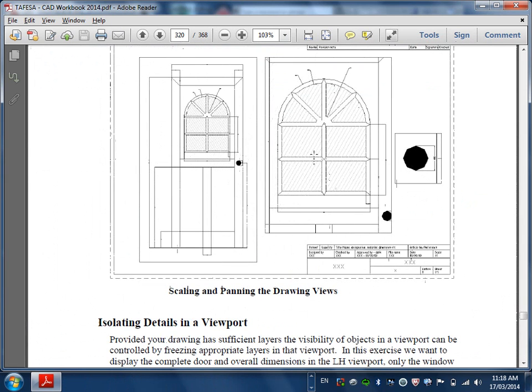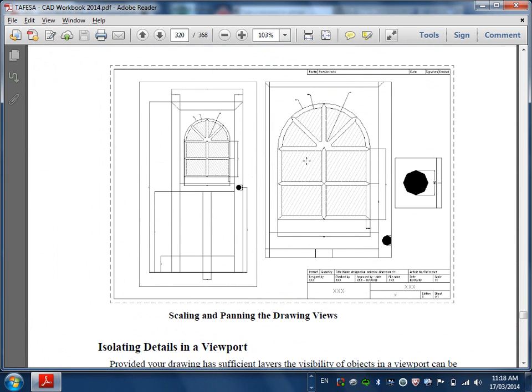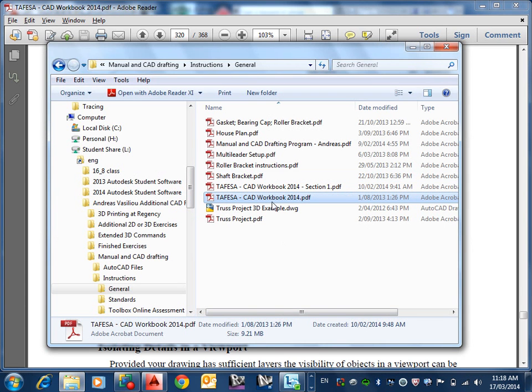So you've got to achieve something like this, but it does tell you how to do it in a different way, basically not using annotative dimensions, which is the way we're heading. So I'll redo the similar sort of thing, not exactly all the dimensions like that, but using annotative. To start with, I'm going to show you how to set up an annotative dimension, but then I'll go on and just use my own template that's got everything set up in there.